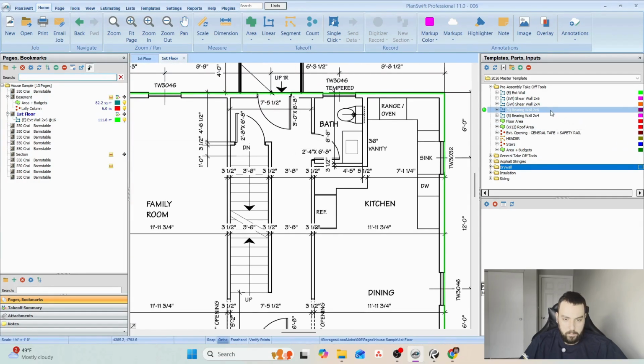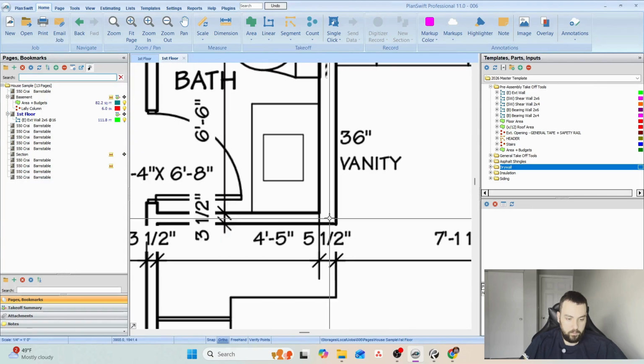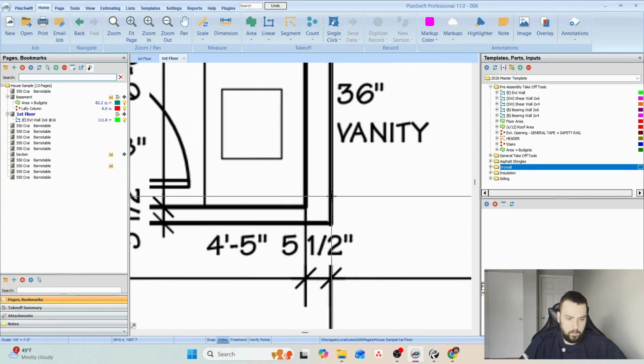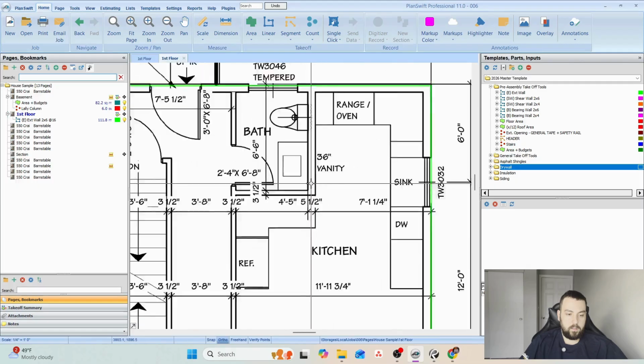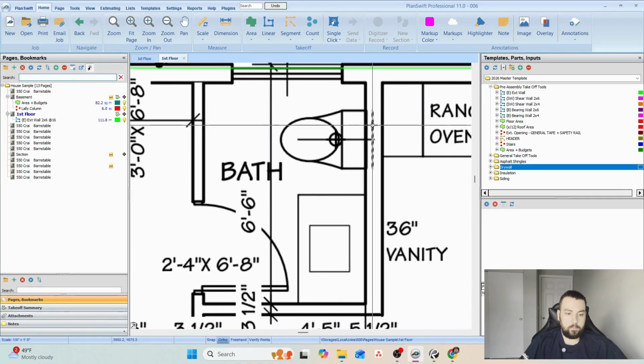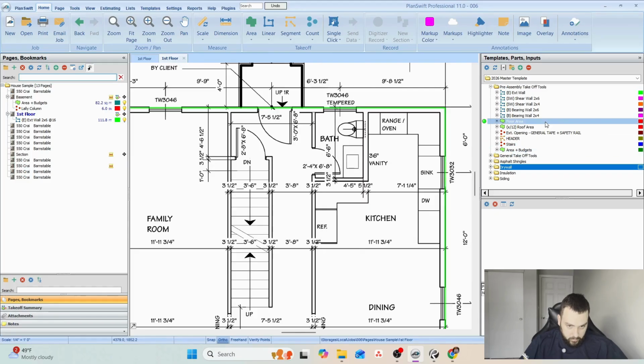So let's go by bearing wall. In my experience, you can see the difference in thickness of the wall, and we can also see the dimension here, 5.5. So this one is a 2x6, this one is 2x4s. This is a 2x6 probably because of the bath and plumbing. So pretty much everything is a 2x4 bearing wall.